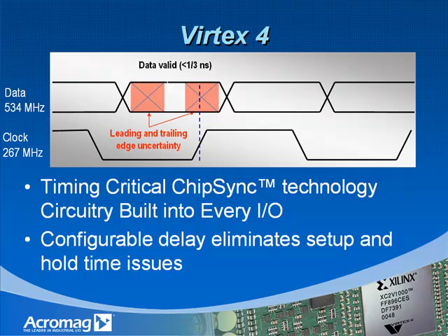The Virtex-4 device has ChipSync technology built into every I/O pin. ChipSync can be used to control the delay of the given I/O pin to eliminate setup and hold time issues.